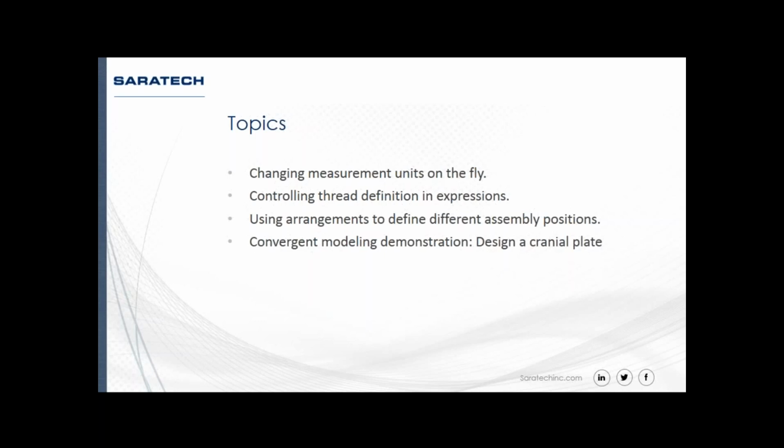Changing measurement units on the fly, controlling thread definition in expressions, using arrangements to define different assembly positions, and then a convergent modeling demonstration where we'll design a cranial plate. And I will be going through what exactly this means as I go through the demonstration. So with that, let me switch over to NX, and we'll go over the first topic, which is changing measurement units.